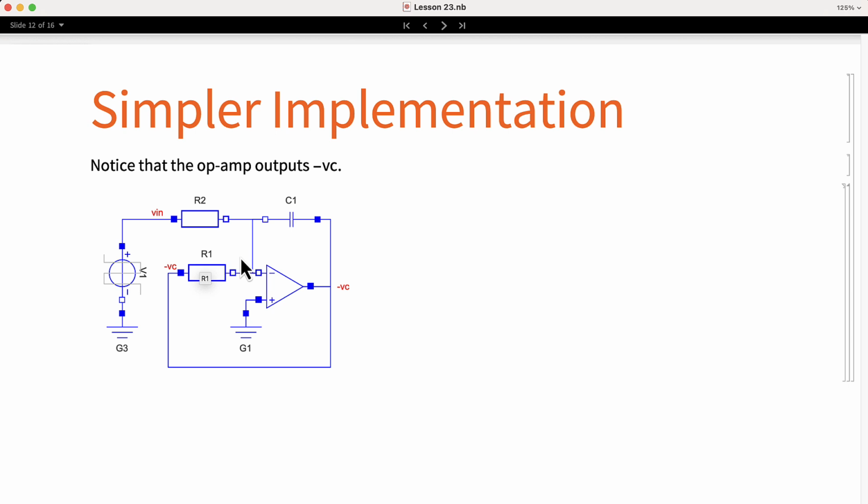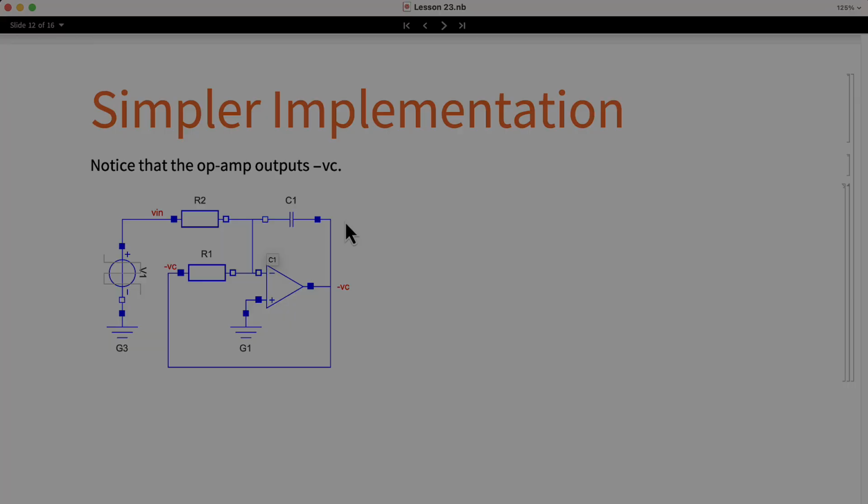In order to match the differential equation, both resistors must have the same value of R, and the capacitor should be the same value as the original RC circuit. This simple circuit behaves as a filter. But why do we add complexity just to get the same result that we were getting with one resistor and one capacitor? Let's compare the RC circuit against this implementation in order to understand the advantages and disadvantages.